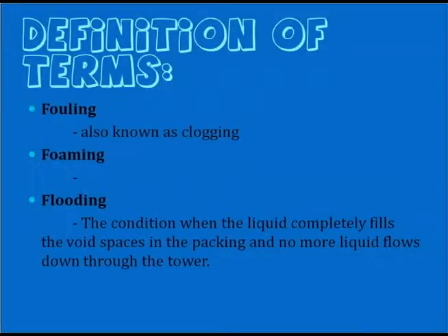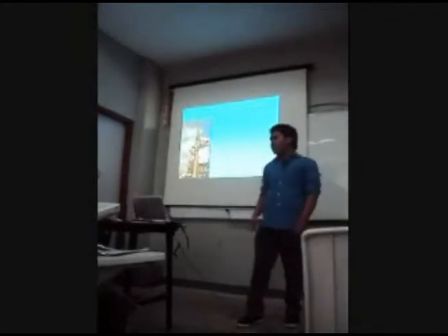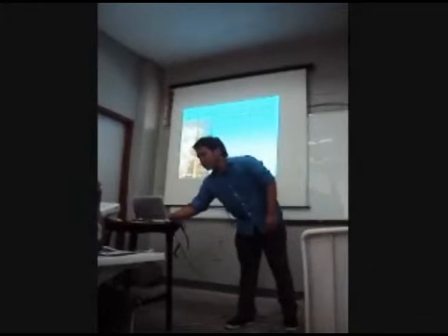So for the design of gas absorption systems, you have two types of equipment. The first one is the tray or plate tower. It is often used in order to efficiently contact the vapor and liquid in the absorption process. The liquid is maintained on the tray surface and prevented from flowing down through the holes by the kinetic energy of the gas or by using bubble caps in its holes. Overflowing liquid enters the downspout to the next tray below, and gas flows through the holes or bubble caps and passes through the flowing liquid.